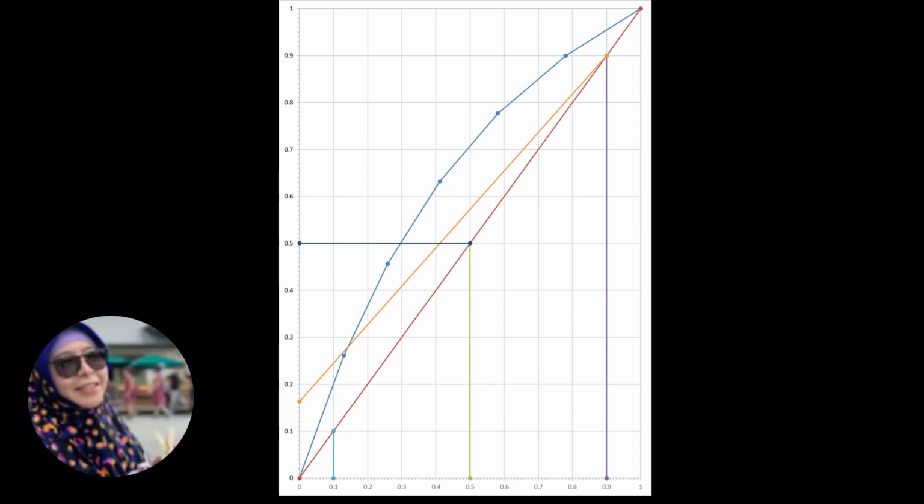For the SOL, you draw a line extending until it meets the intersection between the enriching operating line and the q operating line. Then you can start drawing the stages to calculate the theoretical number of stages.